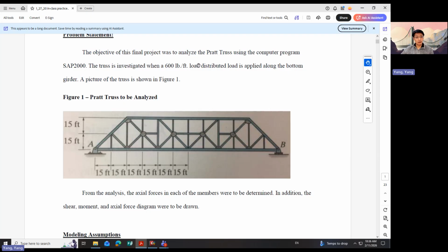And we are going to apply a load at the very bottom chord so that we can tell, definitely we will see some bending for the bottom chord or some bending for the top chord, and some axial forces in the smaller members in the interior panel over here. So we will use the Midas general. So the geometry is pretty straightforward.